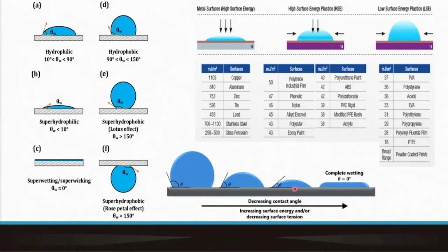On the other hand, if we take any real liquid droplet and spread it over the surface, it will subtend varying degrees of angles, and as it changes from super hydrophilicity to hydrophobicity, the angle increases, and this is how we measure the angle subtended. So in other words, we have to ensure that the angle is part of the liquid for which we are trying to measure the angle. If you take the conjugate angle, then you are making a mistake.